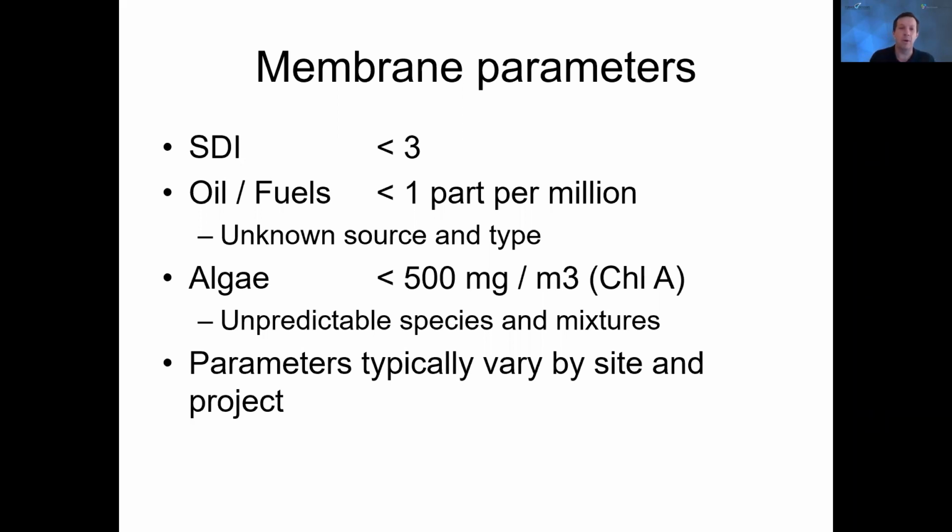And so some are going to have much, much higher responses than others. When we set these things up for measuring chlorophyll A, we're looking at the most common chlorophyll that is in the largest range of phytoplankton or algae that can be in the water. And for those, most of the time we've seen the requirement of less than 500 milligrams per cubic meter, which is about 0.5 ppm.